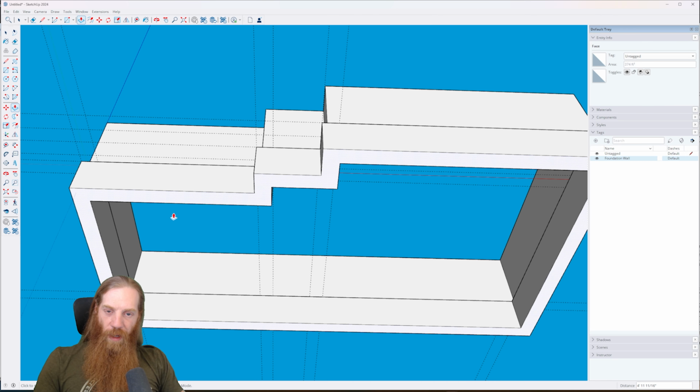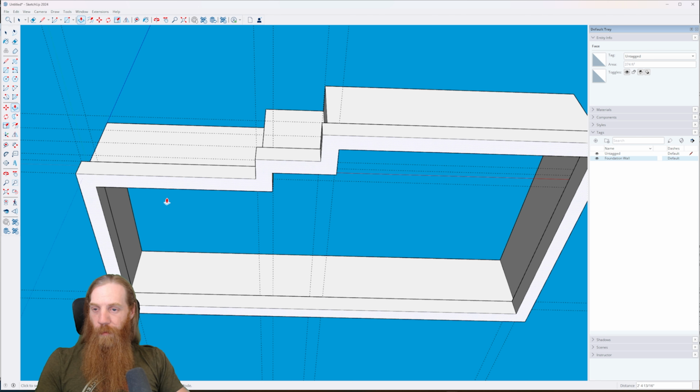Now, if you don't know the depth of your footings, the height of the footings, if you will, go look it up in the plans or talk to a local engineer and figure out what's usually done in your area. These plans, just like we used for the width of the footings, also say that the height of the footings should be a minimum of 1 foot. I will tell you from experience, that's pretty standard, 1 foot height for footings. So we're going to stick with that.